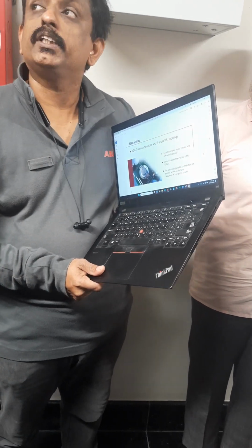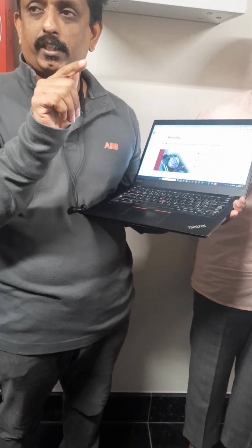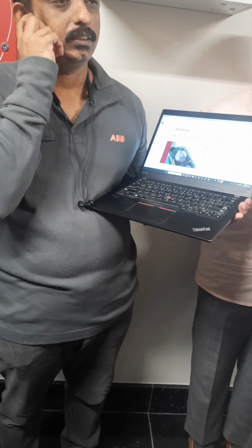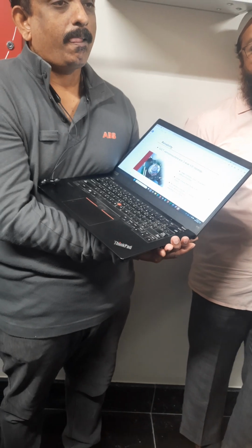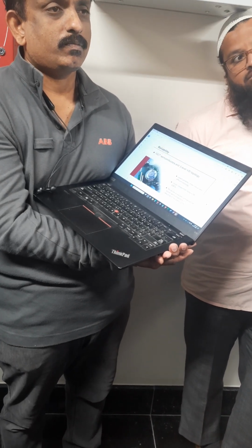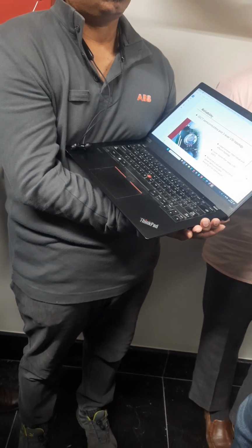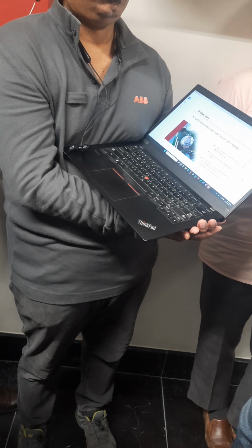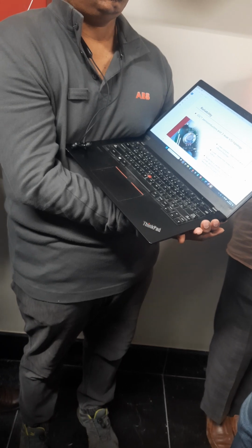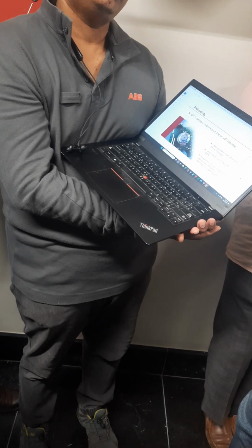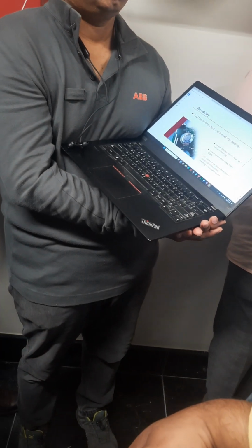We can run in manual, because from the control board itself we can make it local. Then you can give the reference and start it. If SCADA is totally lost in the building, you can run. Yes, the chiller operator will make it manual mode, no issue. There is a provision for running in manual, and auto also we can run.